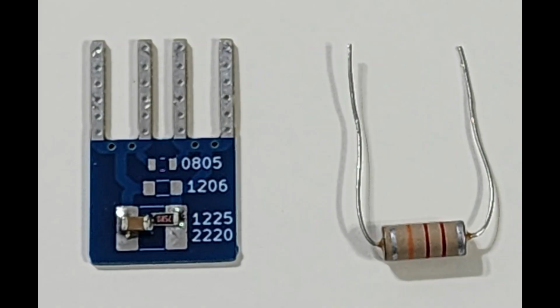On the page, you see two circuits. On the right is an inductor with a value of about 26.5 millihenries and a series resistance of approximately 74 ohms. On the left, you see a test board, and on that test board is mounted a series RC circuit. The resistor is 75 ohms to try to match the 74 ohms of the inductor. And the capacitance would be selected to be L over R squared, or approximately 4.7 microfarads.